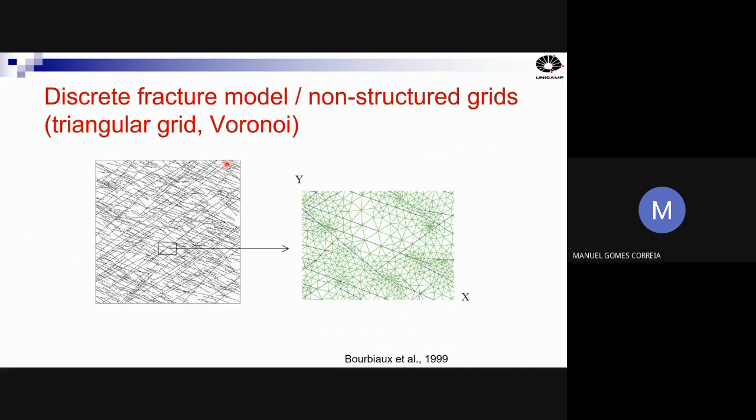But the problem is not only the dual porosity models. You also have the upscaling techniques that I talked about, the analytical methods, that is the Oda method, where a lot of information is lost in that kind of upscaling method. Normally it overestimates. The analytical method, the Oda method, is the only method that you can use in the full reservoir because it's faster, but normally it always overestimates permeability.